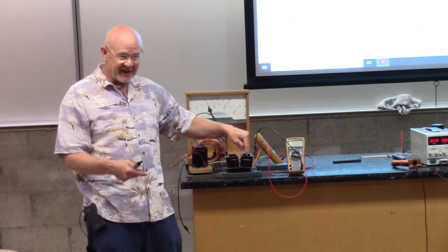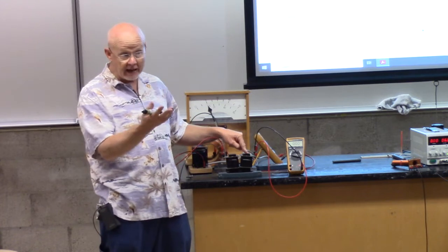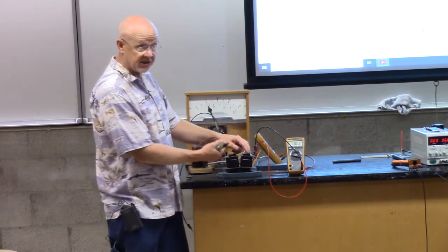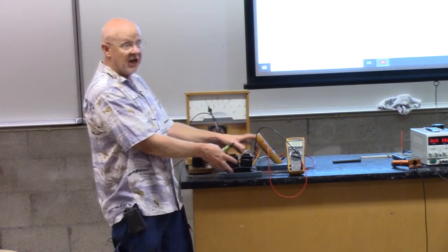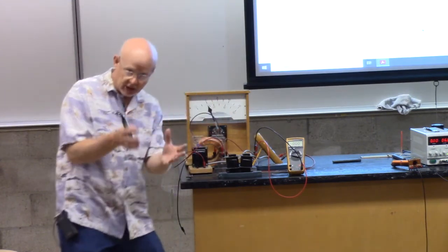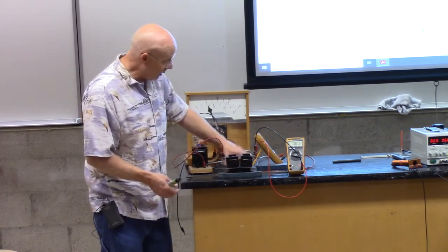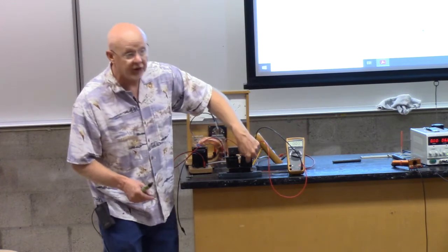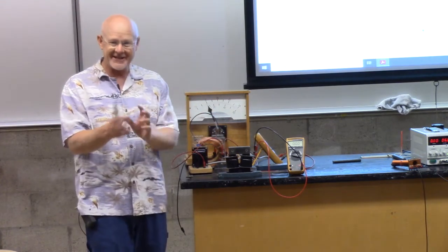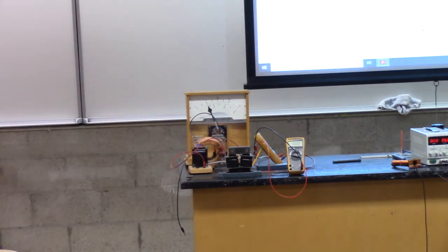And because of Faraday's law, there's going to be a change in flux here, and that's going to make a voltage. Now, there's no point in talking about the direction because this keeps changing, you know, up, down, up, down, up, down. So this is going to be opposite, down, up, down, up, down, up, down, up. But so it's still going to be an AC. So the good news here is I won't get into Lenz's law about what direction it is. I'll just say this was constantly changing. So this one is constantly changing. But I would say how much voltage then is produced in the secondary could be more or less voltage. It doesn't have to be the same. Hence, it transforms.